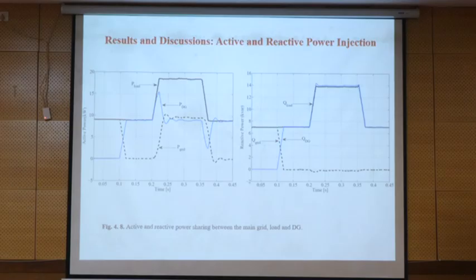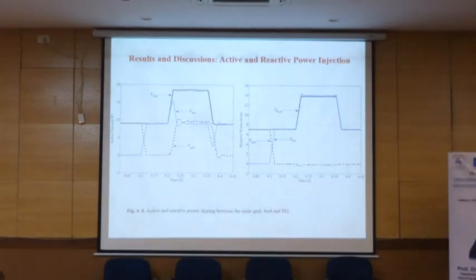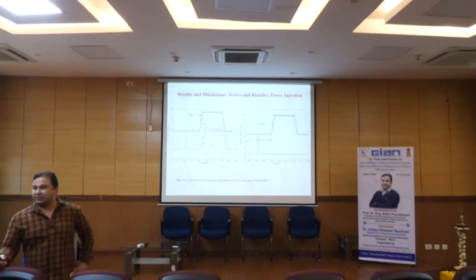Basically, the reason is that when we are talking about the grid, inertia is linked with the frequency, and frequency is linked with the active power. So if you don't have a very strong grid with high inertia, it cannot damp this part. So this part is coming from the impact of the filter, the impact of the PI controller, and lack of inertia, plus some part tuning is also important, for the PI controller.